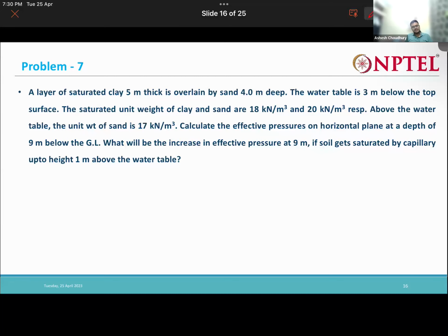Okay, so why is effective stress very important to us? Because all the strength-based failure theories, such as we studied in the shear strength chapter, like the Mohr-Coulomb theory, mostly consider this effective stress, because the main stress is actually mobilized at the contact forces of the soil grains.